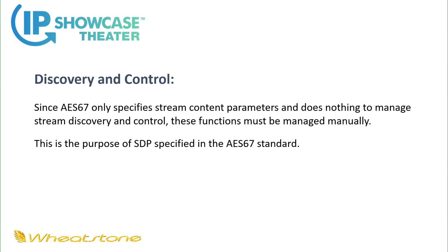AES67 just specifies streaming parameters. It doesn't manage those. It doesn't give you any way of making a connection short of going to a device and actually setting up a stream to receive, versus our system, which is typically using a graphical user interface.